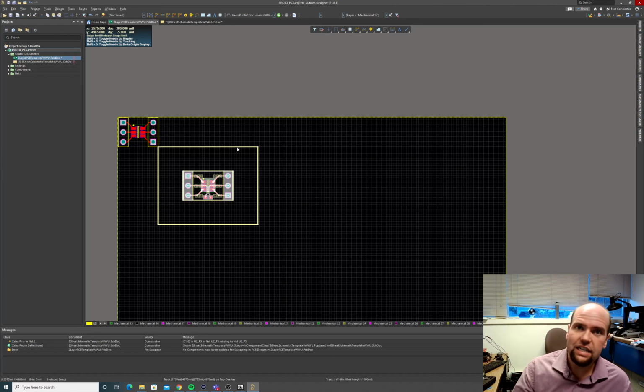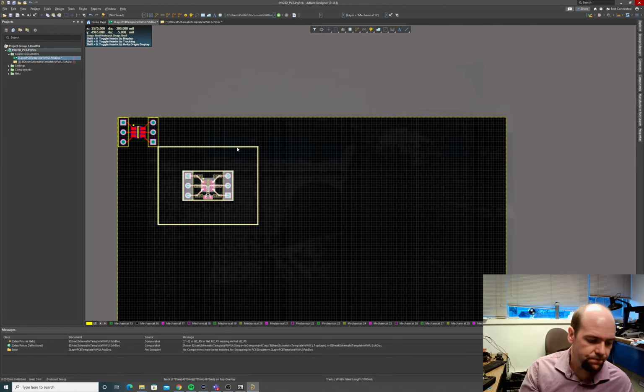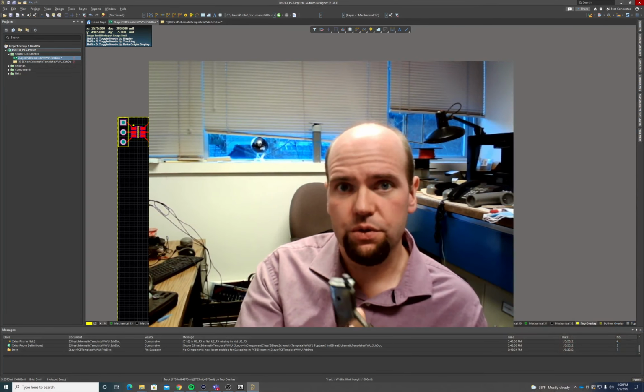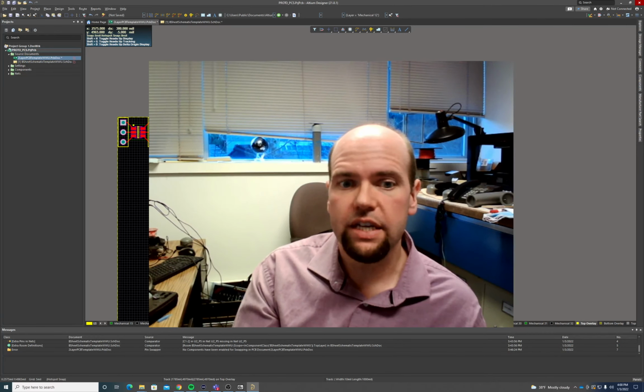That can be really dicey though. If you do that wrong, it's going to be a giant headache for the fab, because as they're trying to make it, your board is too fragile to hold together. So unless you know they're going to be okay with that, you're better off doing a solid board with components that are spaced out, so you can cut them out later, either using a tool like this or using a saw or something like that.